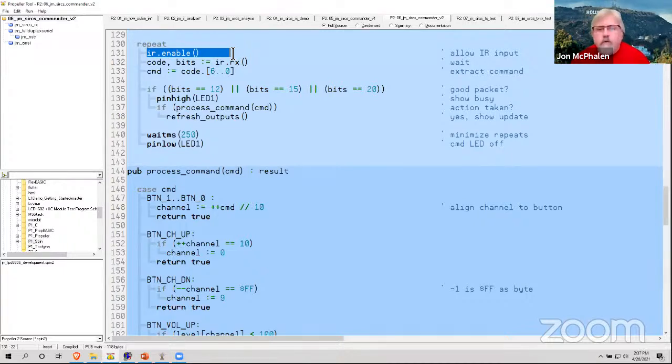I have some things that I've done. One of the things we did to make this more reliable is that, for those of you that were on when we did the one wire protocol, you'll remember the one wire protocol has a CRC value in it. I actually used that CRC method from one wire. I stuck it into the IR packet here because we are sending IR outdoors. So when we send a clone packet over, it includes a CRC. It's made the system far more reliable than the previous system. We know that if it came over, everything's good, including the CRC.